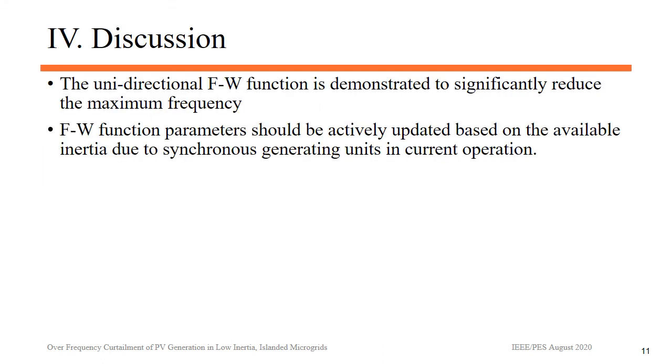In conclusion, the unidirectional frequency watt function is demonstrated to significantly reduce the maximum frequency. Also, the frequency watt function parameters should be actively updated based on the available inertia due to synchronous generating units in current operation.